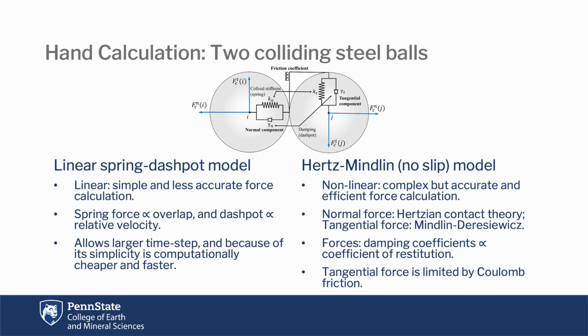So there are two methods. The regular way that we get our frictional force is the coefficient of static or dynamic friction times the normal force, and then there's some other method of calculating it that involves the shear modulus. The minimum value, the smaller value between those two, is what we actually take to be our tangential force.